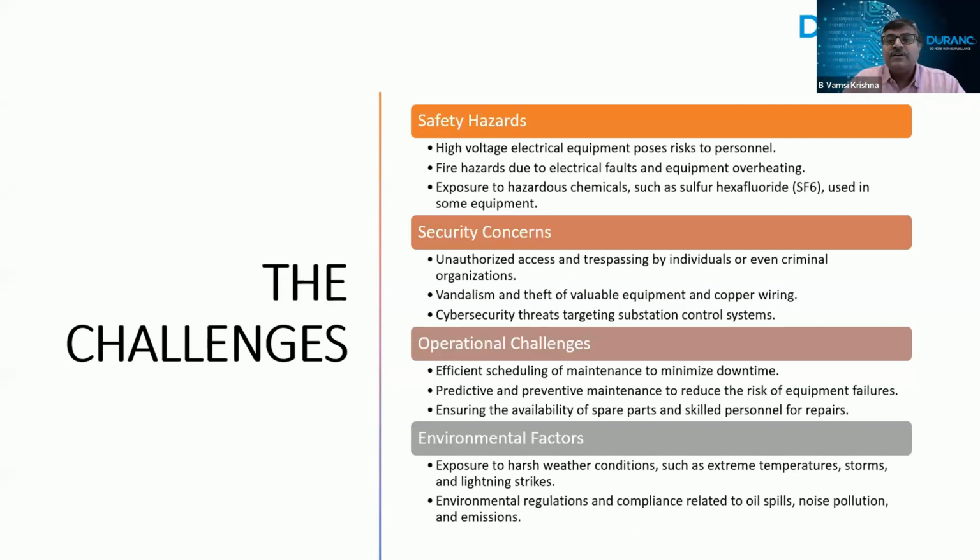Definitely, yes. So in terms of some of the challenges, if we look at maintaining a network of electrical substations, it's a complex and challenging task due to various operational, safety, and security concerns. Some of the challenges are listed here. You are probably more aware of them than we are: the safety hazards with high voltage electrical equipment, the risk that it poses to the personnel, the fire hazards that are possible with electric arcs, etc., and the security concerns in terms of unauthorized people entering, trespassing, theft, or vandalism.